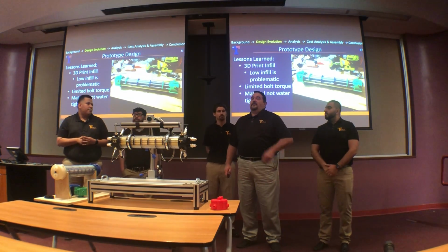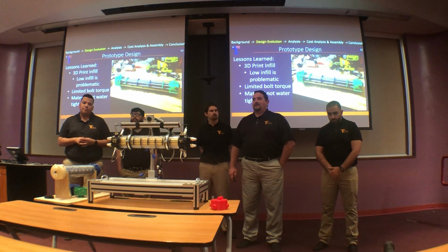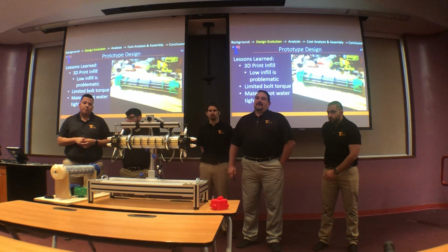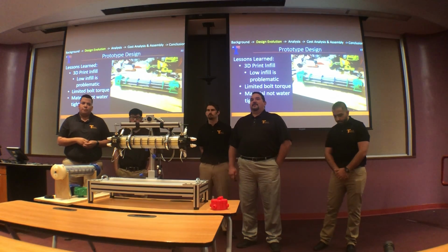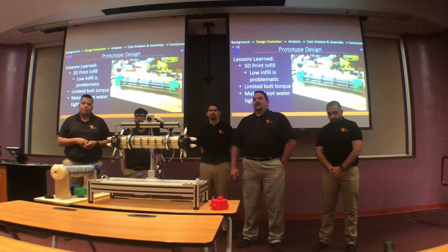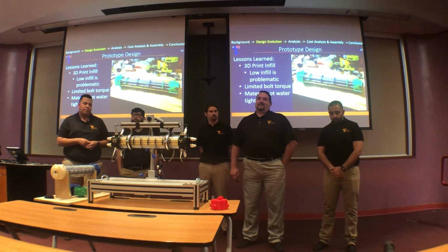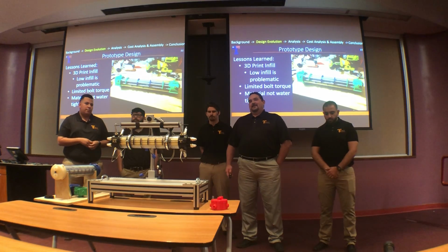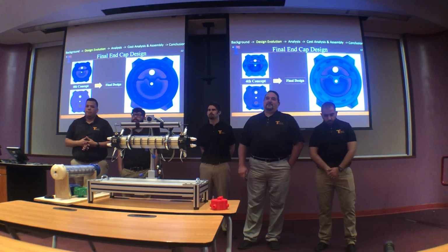So when we got to the third iteration, we thought we were good on our design, but we had some hard lessons learned. We didn't know much about 3D printing. Had a very low infill, I think approximately 20%. So we printed everything out, put it together, and we had issues even tightening the bolts, and the material is not watertight at that percent infill. So we had to kind of go back to the drawing board,